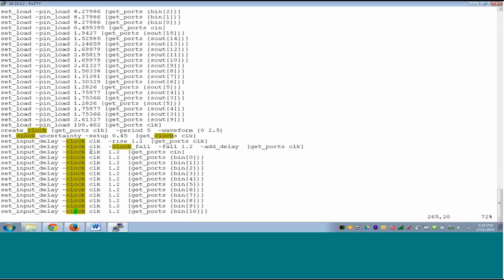So this is where characterize helps you, right? This is where there is a system in place which, from the one basic synthesis that is already done, lets you calculate accurate environment conditions, more accurate than the earlier pass. With each new pass, if you notice, this is simply not a 2-pass procedure. Although a minimum of 2 passes is needed, you can also have a third pass that will still improve accuracy. So many people will do a 1 pass basic plus 2 pass characterize. Many people will do just 1 pass characterize. It just depends on the quality of results that you are getting out of every pass.